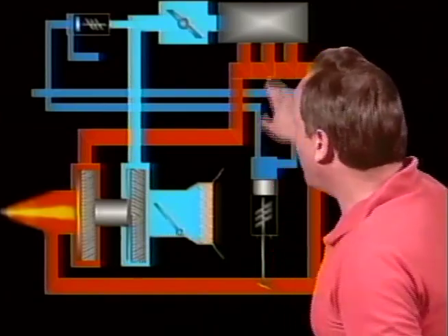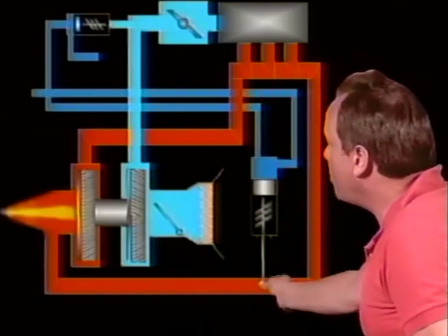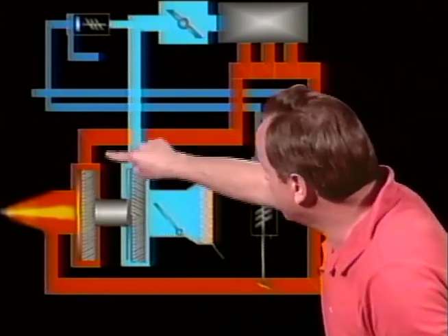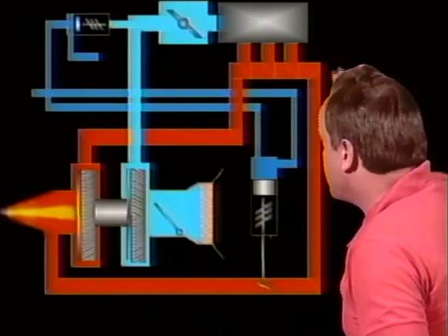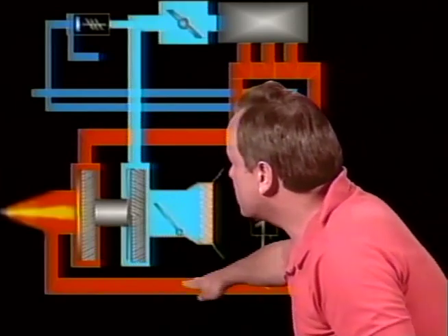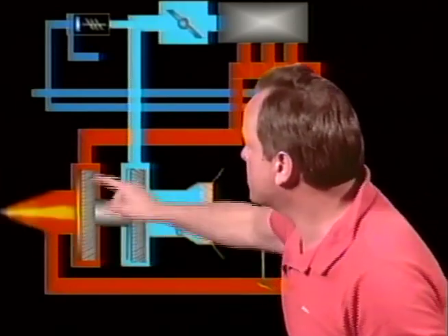That's a turbocharger. By the way, if you have a turbocharger equipped on an aircraft and you don't want to turbocharge at the time, you have a wastegate down here in the exhaust system. You open this wastegate and the exhaust, instead of running past or through the turbine, goes around or bypasses the turbine because the wastegate's open and that's the easier route for the exhaust gases to flow. And so you bypass the turbine and the exhaust goes out without spinning the turbine.